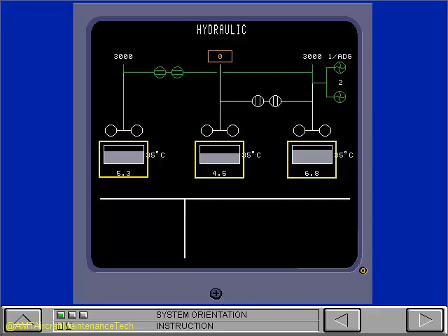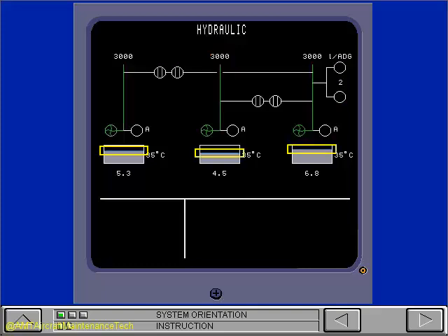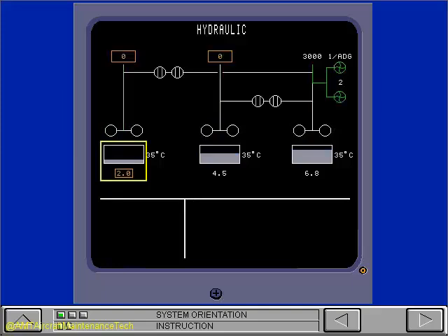Hydraulic fluid quantity shows as a shaded gray area in proportion to the reservoir quantity. The white digits below the reservoir show the quantity in U.S. gallons and in tenths of gallons. When the engines are on and have reached idle, the DEU sends an instruction to the hydraulic synoptic. A cyan line in each reservoir shows an initial flight quantity of hydraulic fluid. When the reservoir has less than 2 1/2 gallons, the digits are amber and show in an amber box.